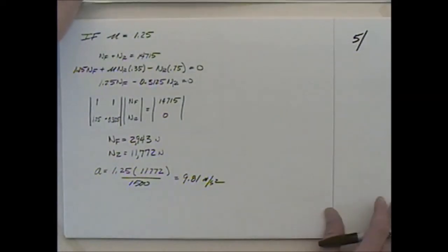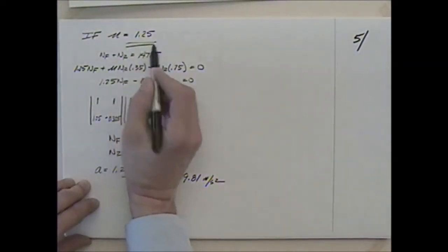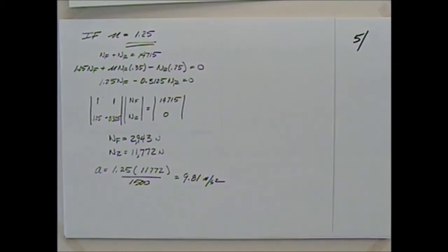So what I said then was, what happens if mu comes up to about 1.25? I did a little bit of research, which means about 30 seconds at Google, and it looks like drag tires get pretty high coefficients of friction, which makes sense. They usually do this in the summertime when the track is fairly hot. They've got a whole process of burning them out to make them sticky. So I think the numbers probably go higher than that. We'll address that. But I said 1.25, which seems like an odd number, but for something that's sticky, it may not be that odd.